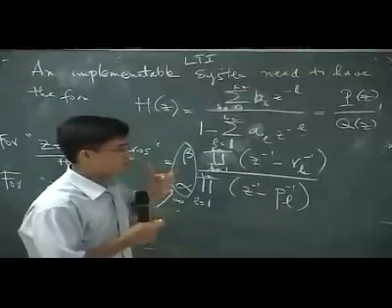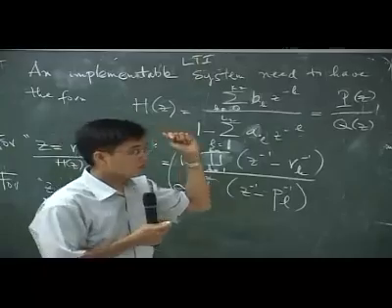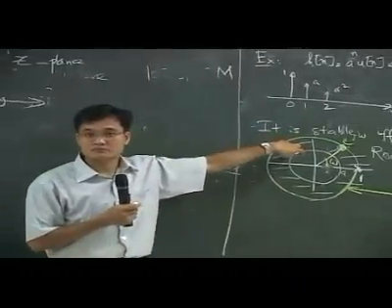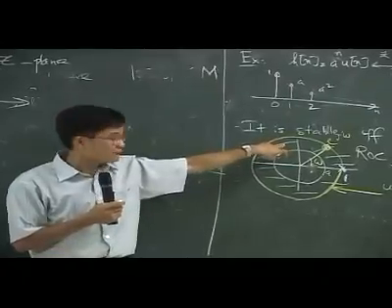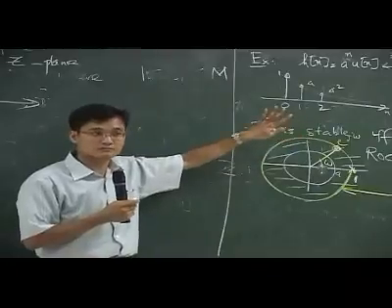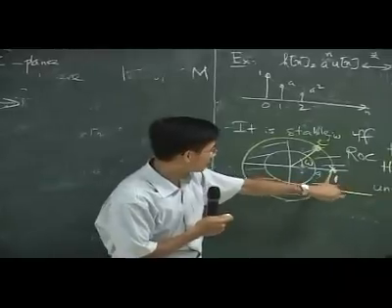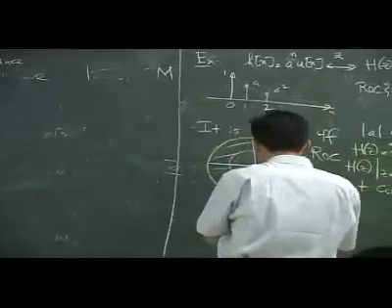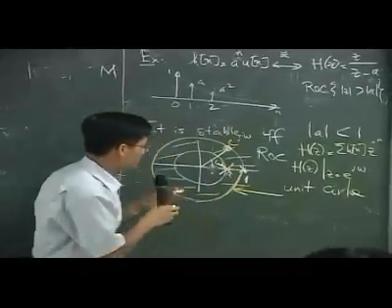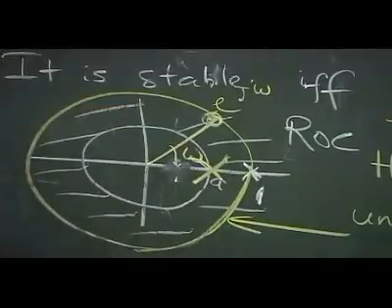Now, the poles are really the place where the thing blows up. So, can the poles be inside the region of convergence? No, by definition, in the region of convergence, the thing had to converge. Give you something, a finite number. So that's why, for example, this filter here, suppose the poles are sitting right here. The ROC is from that inside, right?